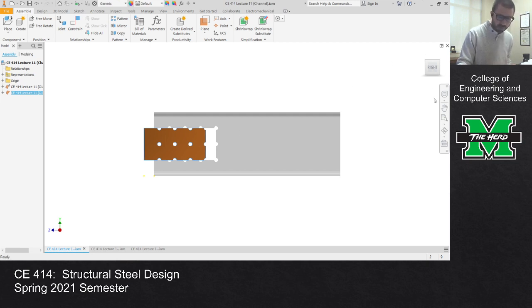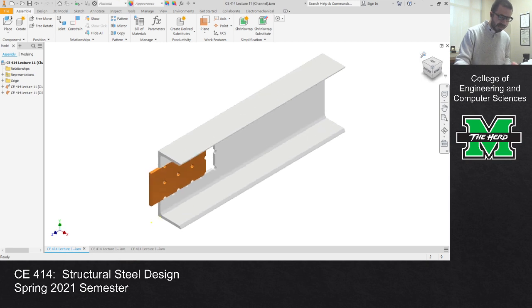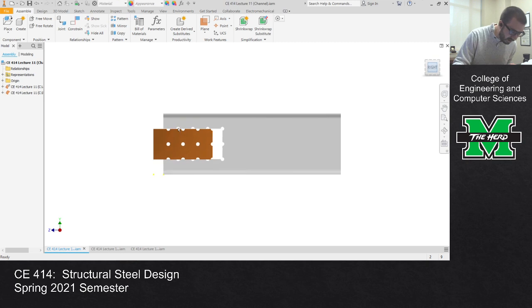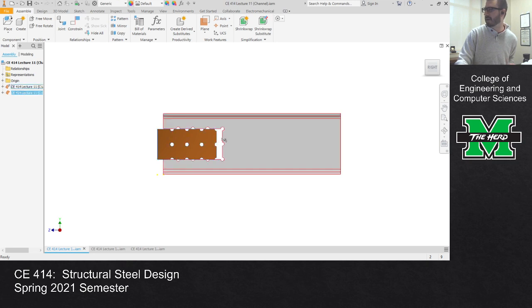That entire chunk is sort of ripping out. In this scenario, you've got this upper portion here, this upper portion there, and this lower portion here. See how it's sliding along the block, so it's experiencing shear. And then this plane over there, where these connections are, is experiencing tension. So shear and tension, and then that section rips out. One of the things we're going to have to address soon is how we identify those failure paths, and how we compute the capacity associated with them.